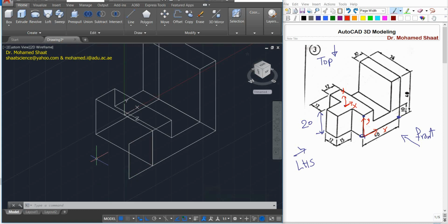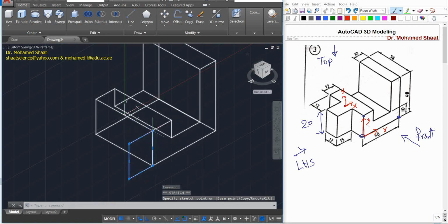It would be different from one to another. Sometimes, this is one of the problems of AutoCAD, that this face would be seen in the front, or it would be seen in the back. Or even it would be seen over this point. So even if it was drawn over the front or at the back, your objective is just to move this point back, because remember, this should be done after you join the shape. Then you're gonna pick this point and move it back here to the midpoint.